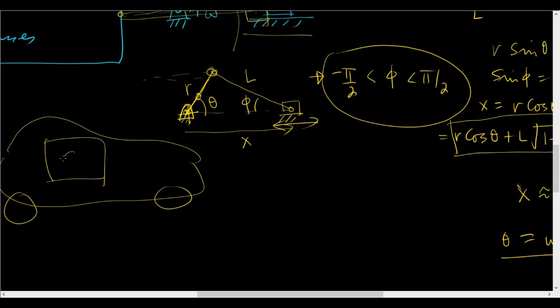If there is an eccentric mass going round and round, there is a force from the frame that is needed to give it that acceleration, and the reaction on the frame is the opposite, and the frame reacts to that. Now you may say, well, I assume the frame is not moving. The motion of the frame is much smaller than the motion of that mass, and so that's a reasonable approximation. If you want to do it more carefully, you can. Nothing really changes. All right, so now we have this, which has possibly some unbalance.